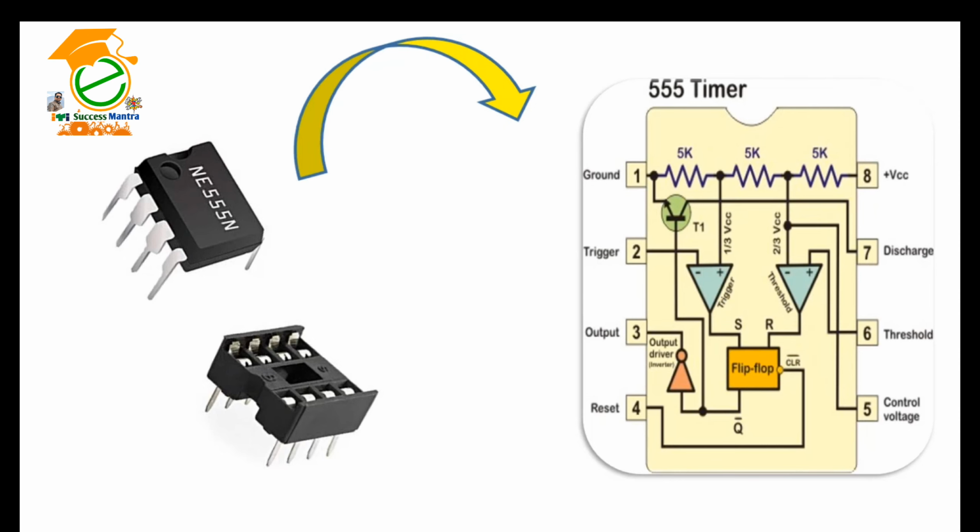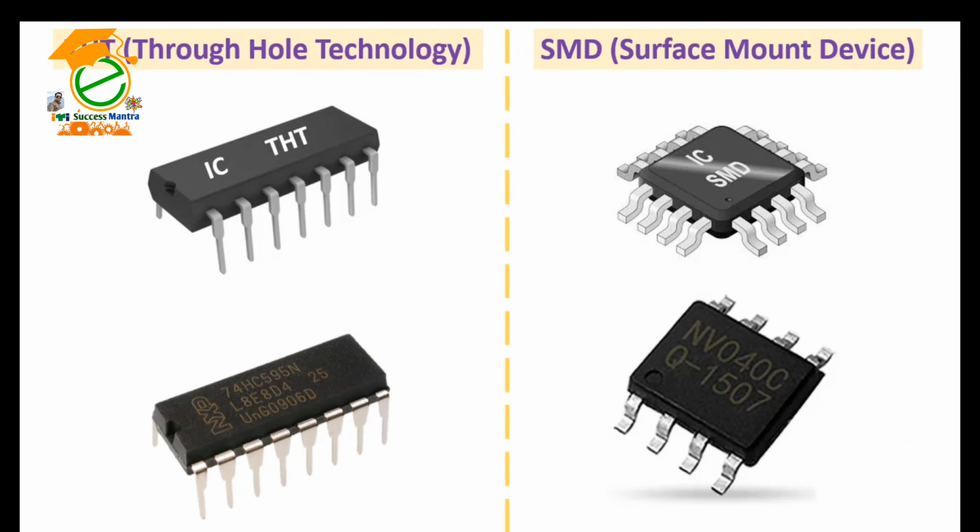On the datasheet, you will learn the functionality of each pin. It should also state the voltage and current ratings of both the chip itself and each individual pin. Integrated circuits come in a variety of different shapes and sizes. As a beginner, you will be mainly working with THT chips. These have pins for through-hole mounting. As you get more advanced, you may consider SMD chips, which are surface mount soldered to one side of a circuit board.